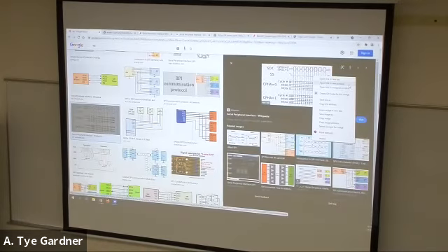Okay, so these are 2 different versions of SPI, 2 different modes, but we'll focus on one. The clock is on the top. As we know, we can trigger either on the rising or the falling. We don't like to trigger on both, right? That causes some issues, and many of you had those issues in your last state machine. So the red line then is the rising of the top and falling of the other. What this means is the SCK can change its CPOL, which is clock polarity. Which clock polarity do I care about?